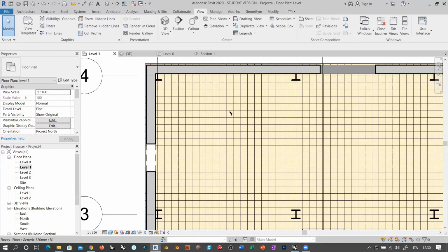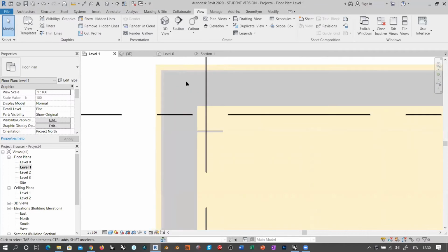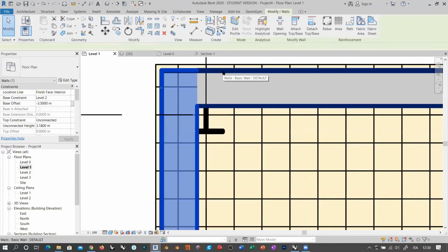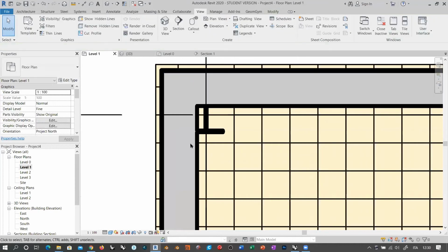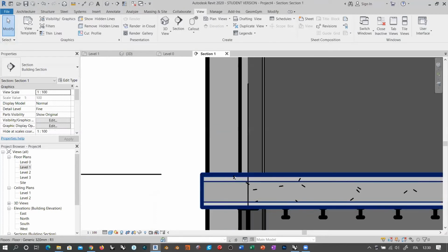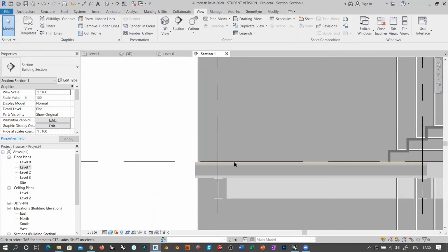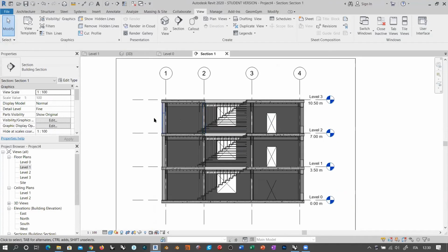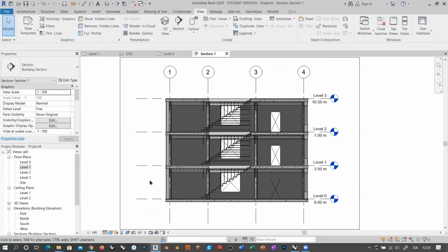So what happened here in Revit? If I select this wall, oh, by the way, Pepe, see that the connection between this wall and this one is taken care of automatically by Revit. Okay. And also, if we go into the section view, you will see that in this case, for example, there is no connection because of how the floor is reaching. Well, actually, it is not aligned with the wall. But if you align things, then you will have the finished layers, for example, turning around these corners. So yeah, connections are automatically created during this export-import process.